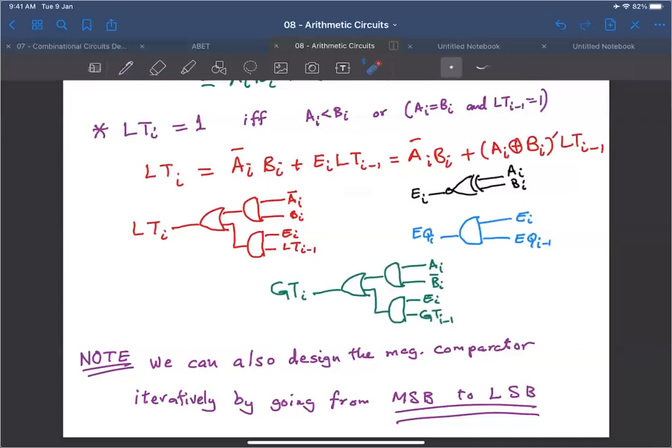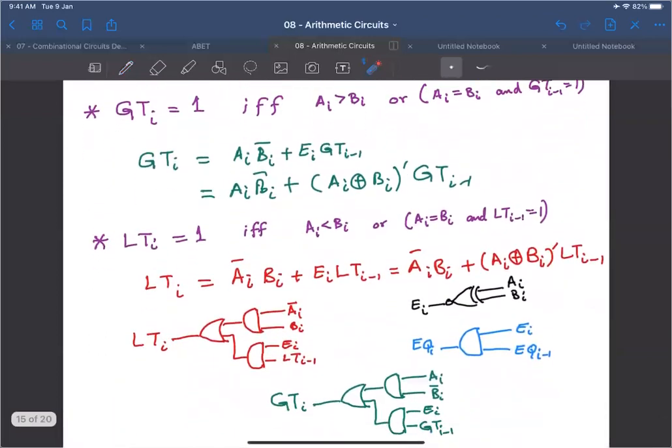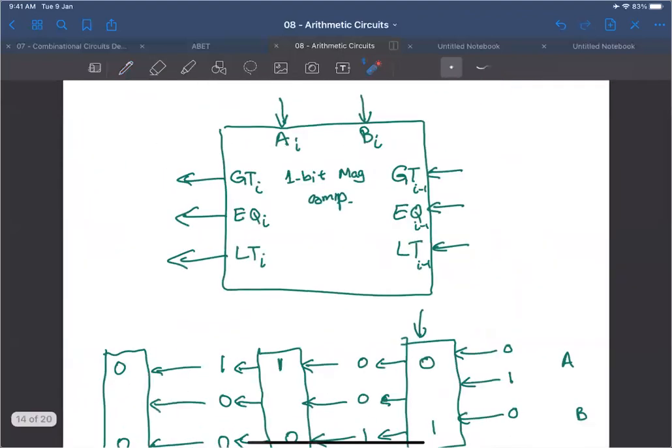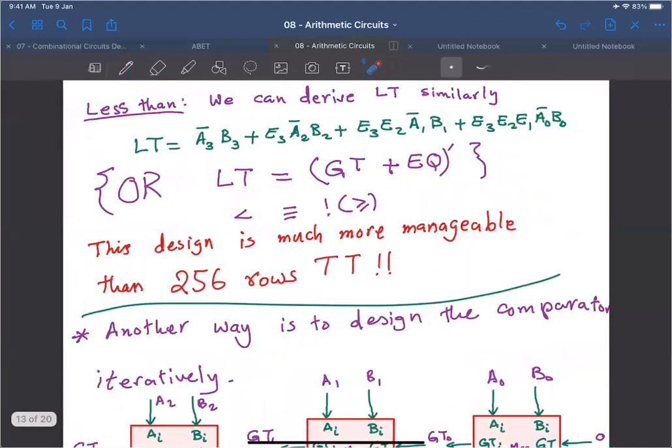Doctor, what is the benefit of using one of each of these different approaches? Okay, excellent question. Notice the design of the cell here. How many gates did we use? Each cell has 1, 2, 3, 4, 5, 6, 7, 8 gates, plus some inverters, of course. So 8 gates for the whole cell. And so our cell is composed of 8 gates only.